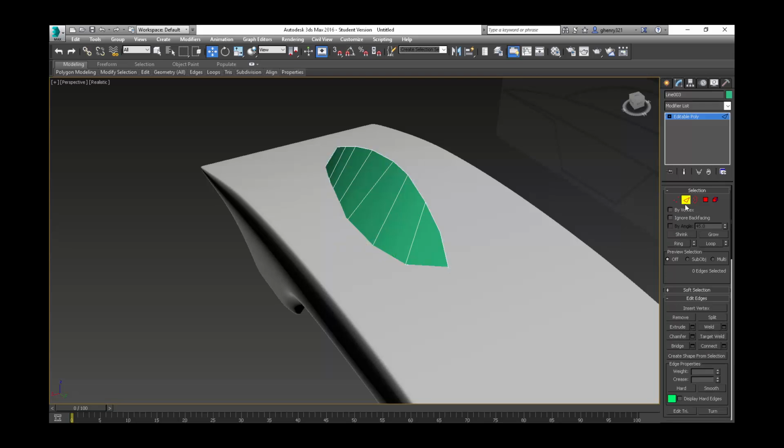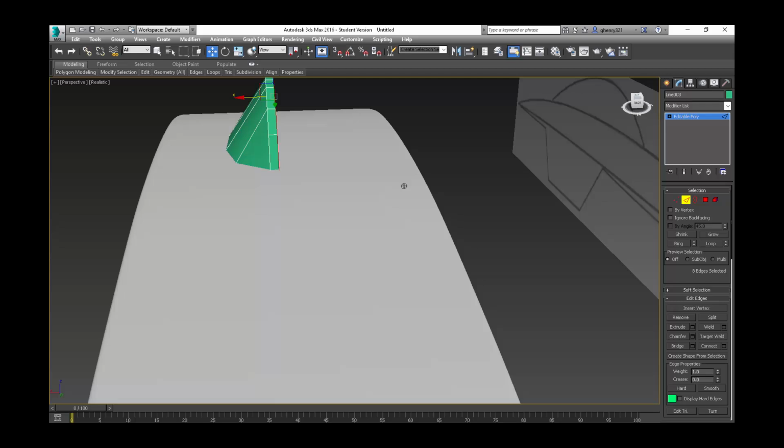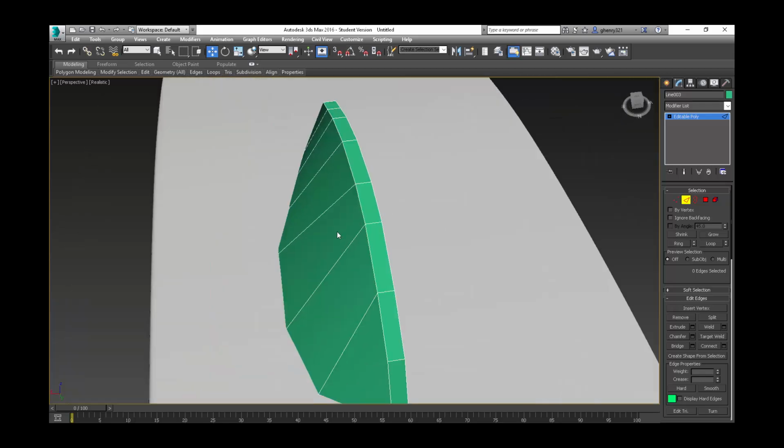I'm going to click line. I'm going to double click this line that goes around the outside rim, and I'm also going to click control and click this line as well. Then I'm going to hold shift down and drag this out. When you hold shift down, it allows you to kind of continue on any old line that you have. So if I select a line here, hold shift and drag, I can keep dragging it out. So we'll keep working on this in the next video.